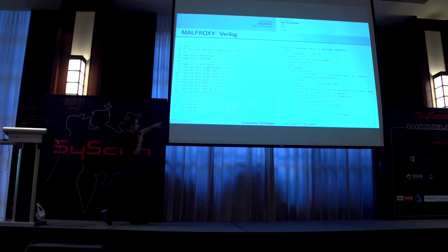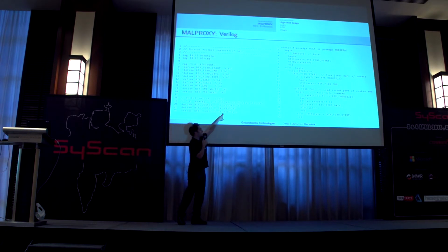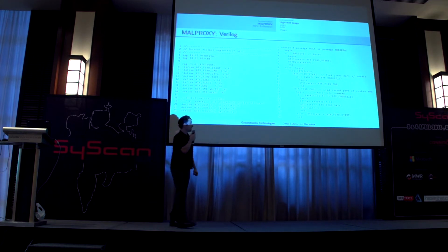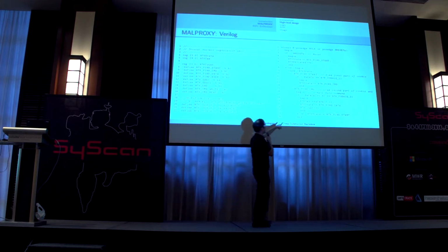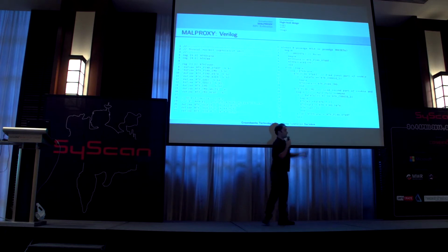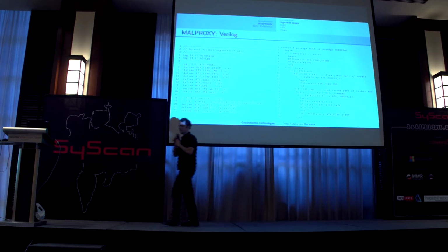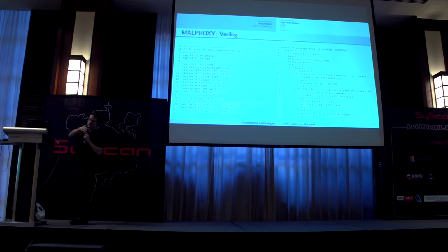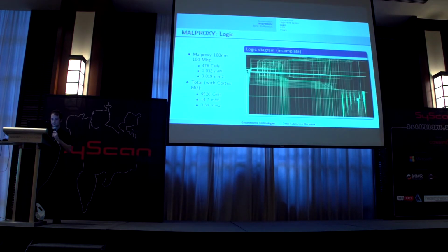We can see here there are the cookies. There's the magic numbers that have to pass through the bus to activate the backdoor. The backdoor is basically a bus operation. It's very simple. Just take control of the bus, write data, or extract data from the bus.